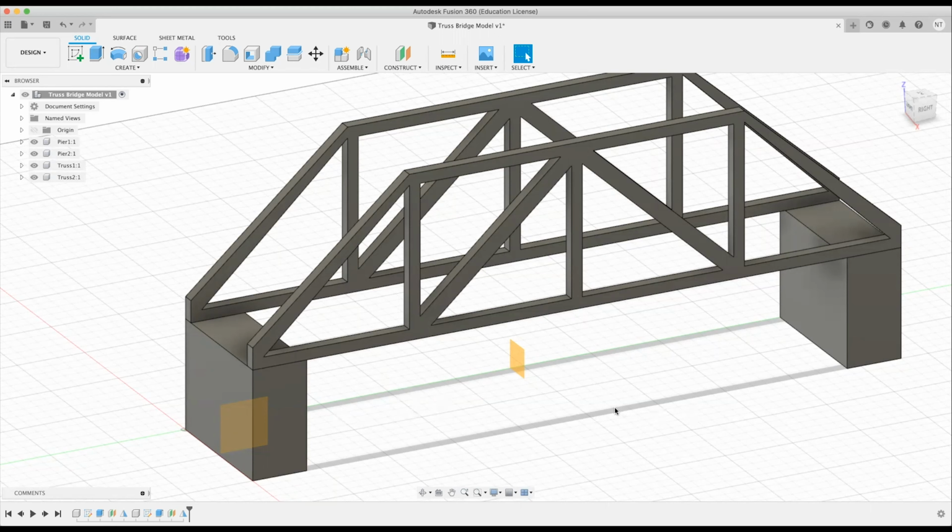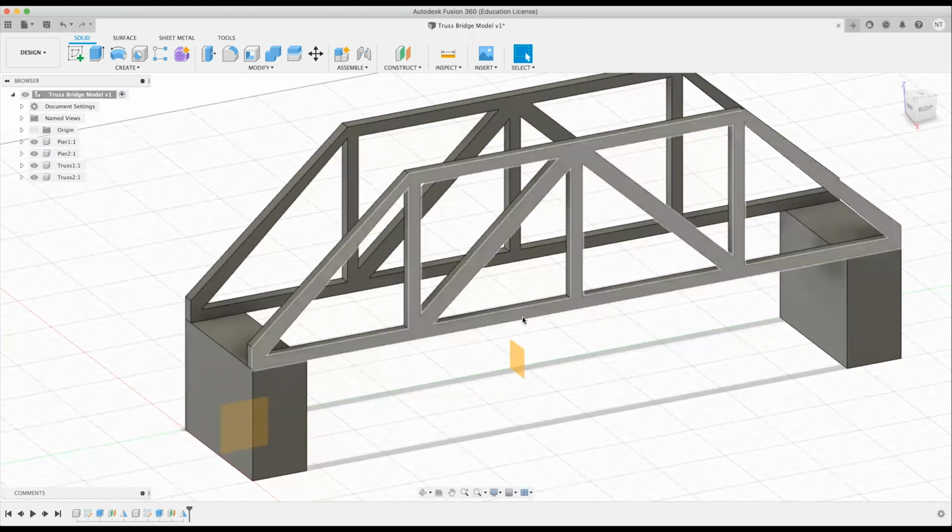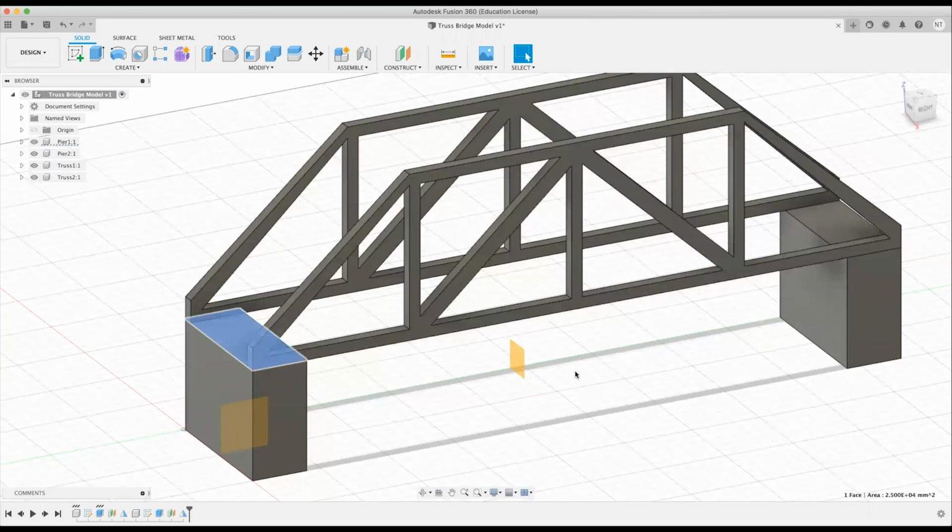And what normally happens is when you have a pier, you have what's called a pier cap, and I might put some video footage over here to better demonstrate what I'm explaining. You normally have a pier cap that rests on top of your piers, which can be either rectangular, circular, piles or columns, however you want to design it. On top of your piers are what are called bearings. These bearings' function is to transfer load from your girders to your pile cap. And these girders usually run parallel to the direction of travel. So you would have a girder that goes lengthwise with the bridge, connected to a bearing, connected to your pile cap, connected to your piles, which bring the loads to the foundation.